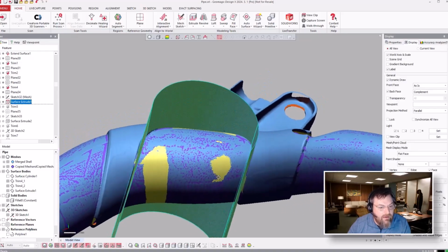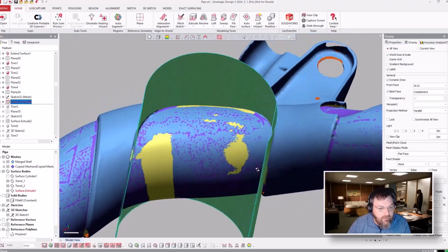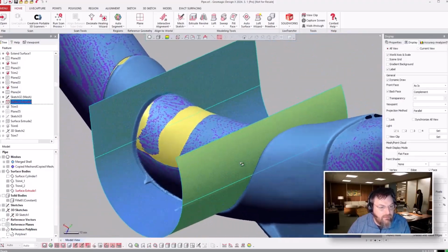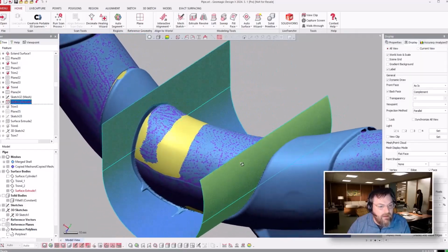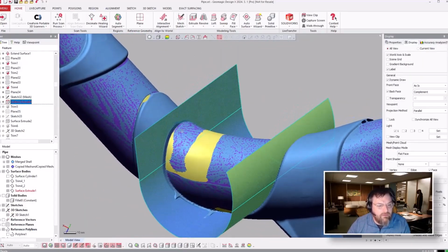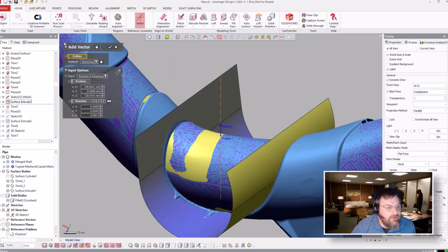So now as you look at this area, it's all one extrude cut away, right? And there's a variety of ways of working with this. One thing that you can do, I will say, is in your reference geometry under vector, you can select geometry.